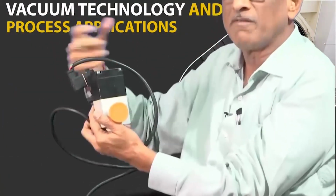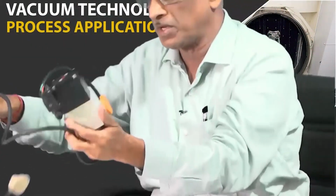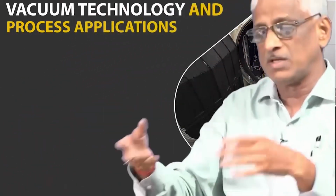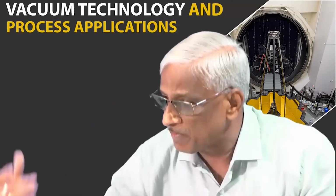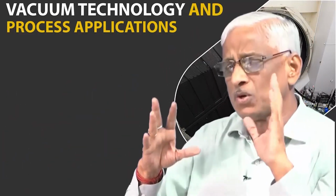Similarly, gate valves, varieties of automation are coming nowadays. So, different flanges, different couplings, different valves, different blind flanges, for example, high vacuum or normal vacuum, you have to select properly and decide your components. So that degassing is minimum, convenience is maximum, and your comfort is very good, and it will not be leaky. It should not produce leaks.